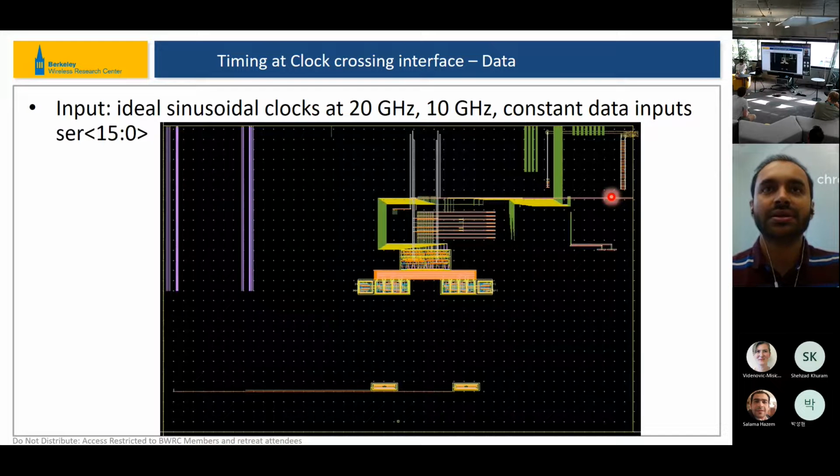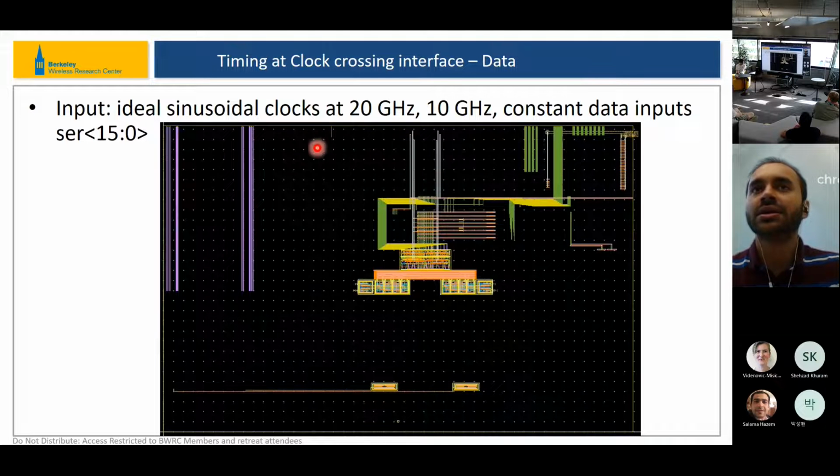And so this is what this new layout looks like. If you compare with the previous picture, you can see that the inductors are gone, the RDAC, and all these clock circuits are gone, the low speed serializers are gone, and I have only generated the blocks that are necessary, but I do keep all the global routing. So the routing parasitics are still taken into account while doing this simulation.